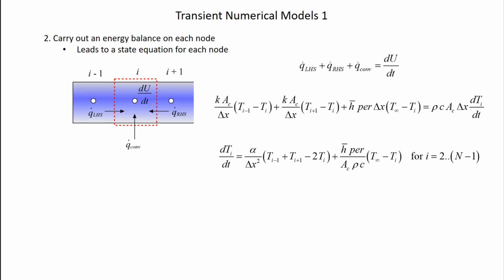I think about in equals out plus stored, right? Because this is an energy balance. So I'm going to define all of these terms as in. This is conduction from the left, conduction from the right, and convection. So these are all ins. There's no outs the way I've defined the flows, and then there's a stored term, right?